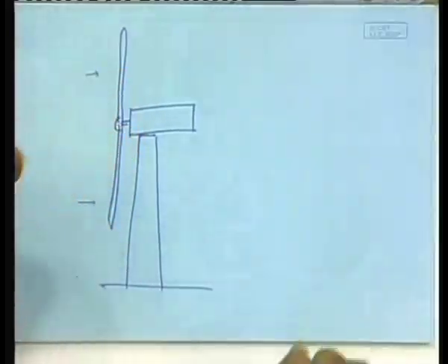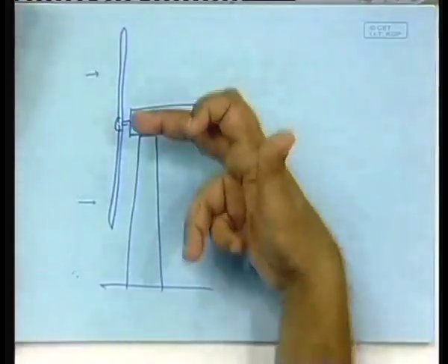As a result, this torque pulsation, what does it do? The torque pulsation is felt somewhere here. The torque pulsation essentially sometimes leads to blade failures. So, it is generally known that the 3-bladed turbines are structurally stronger, less prone to failure than the 2-bladed turbines. That is why, even though economics works against it, many companies choose 3-bladed turbines.